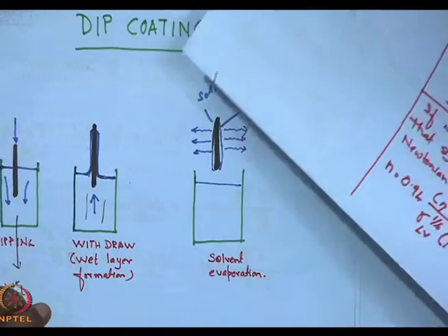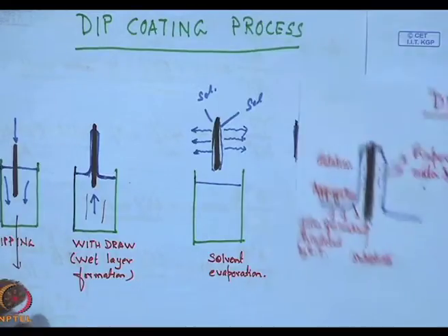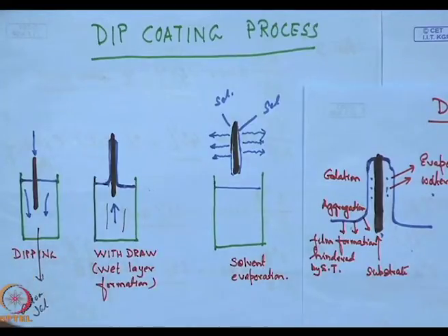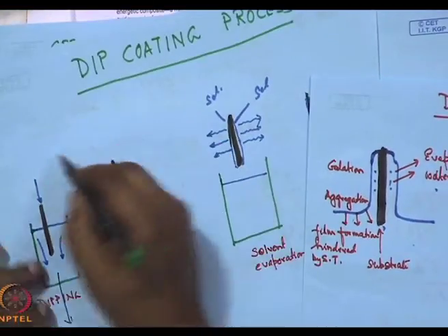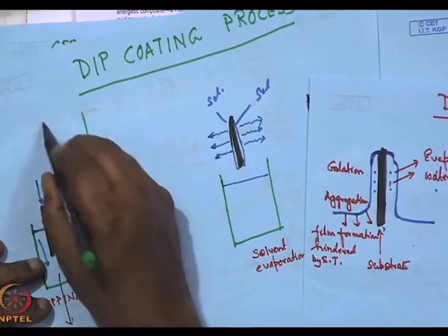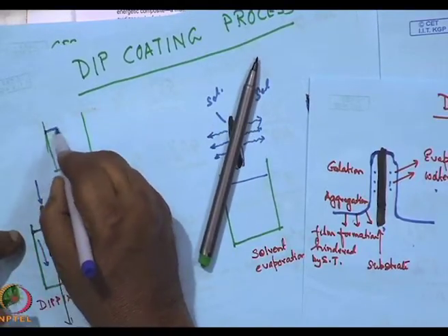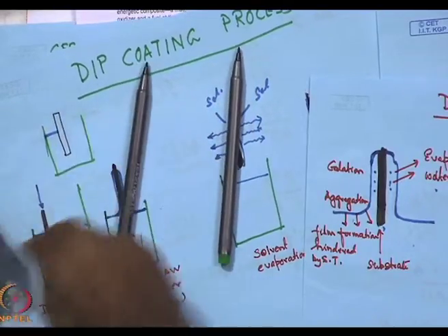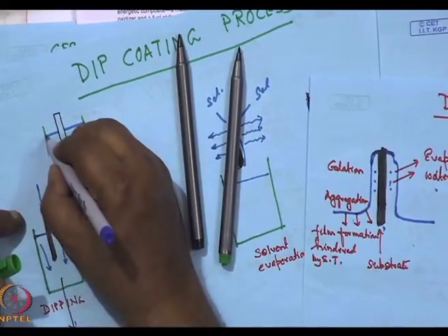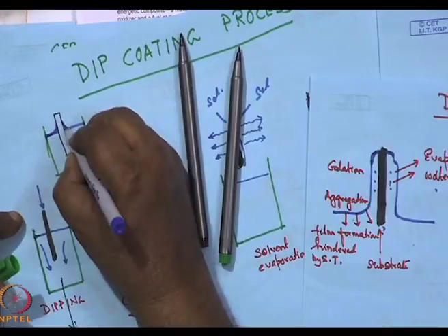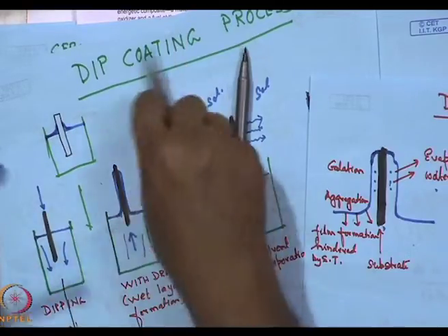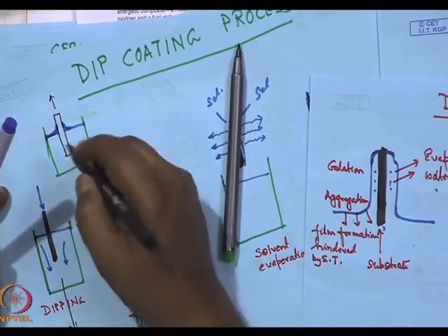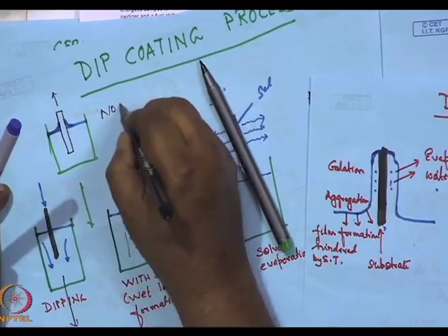Now, one of the most important things is during this withdrawing, that is, if I put in an additional diagram over here where I had the liquid, the liquid surface would be bent. During this withdrawal step, it is very, very important that no turbulence occurs.